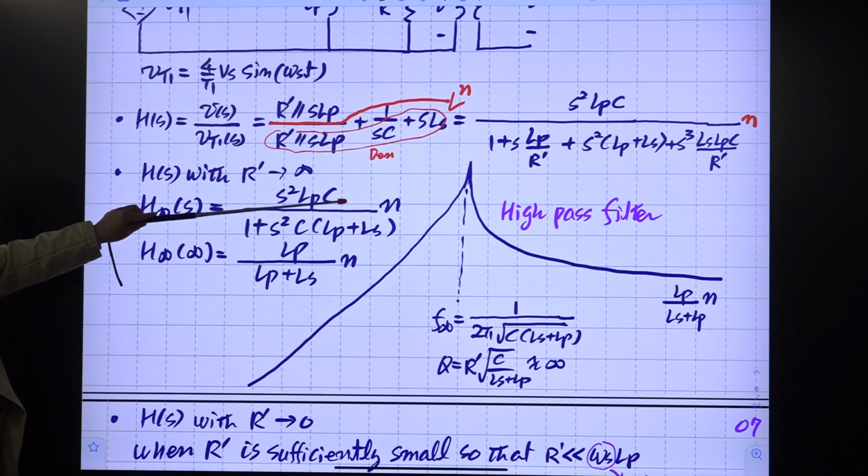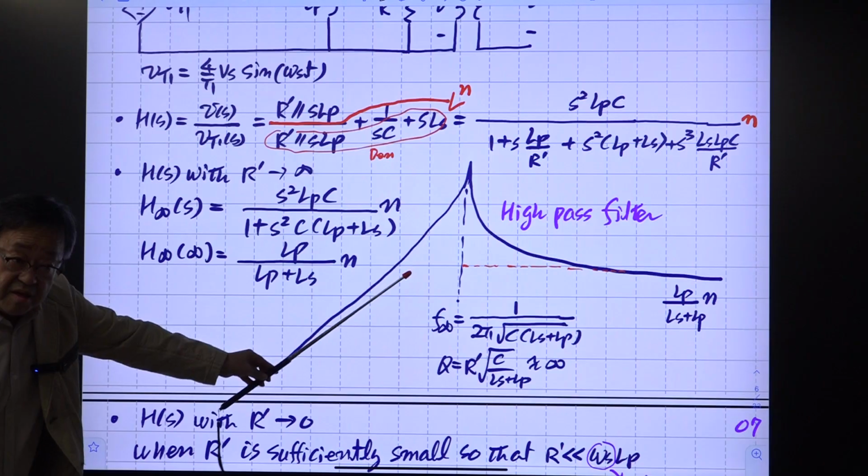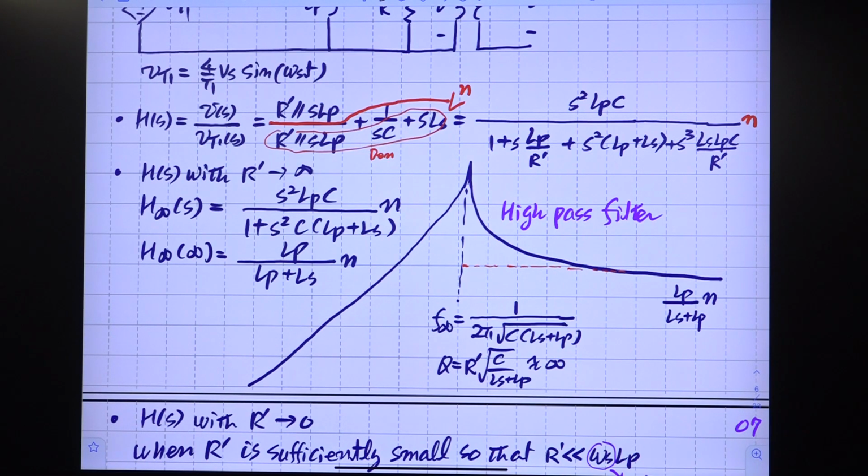First you have this, which is the double integration. So if you plot the asymptote, I decided not to explain every detail about the frequency response for the time being. Maybe some of you are not very familiar with this type of analysis. This is very easy actually. So this is double integration, so the slope is increasing by 40 dB per decade. We use a symbol of +2 to indicate the 40 dB per decade positive slope. So we have +2 slope.